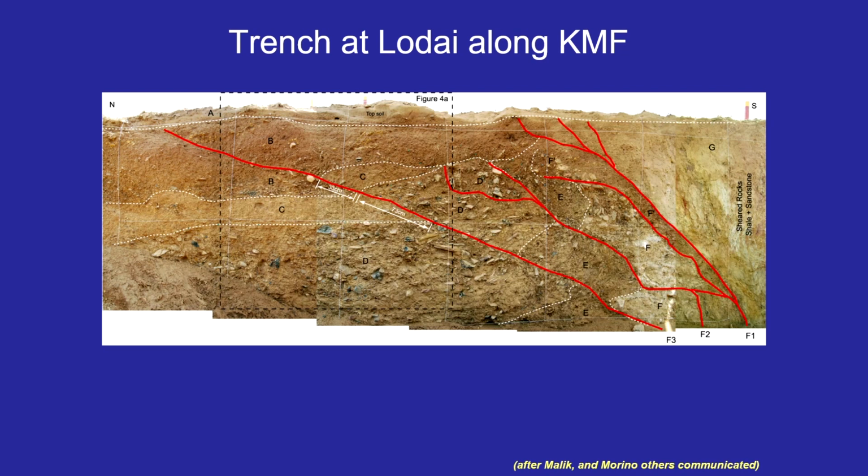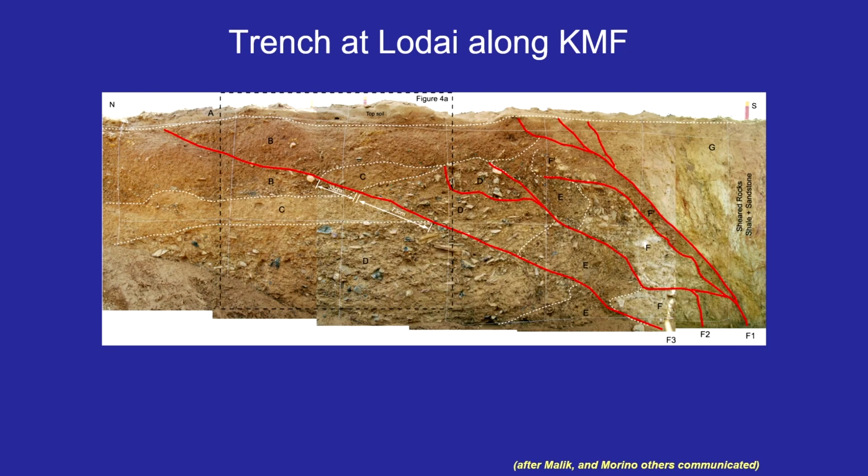This part I have already discussed, so I will just move forward to how we identify the different litho units. And before going into identification of different litho units or sedimentary units, we need to clean the trench rigorously. Either you clean it by spraying water on the trench to remove the dust, or you use brushes to clean it, and then demarcate the boundaries, that is, the bounding surfaces between different sedimentary units exposed in the trench, and also look for the cross cutting relationships, which is what we call the unconformities. The breaks we see in the litho units have to be clearly identified and demarcated.